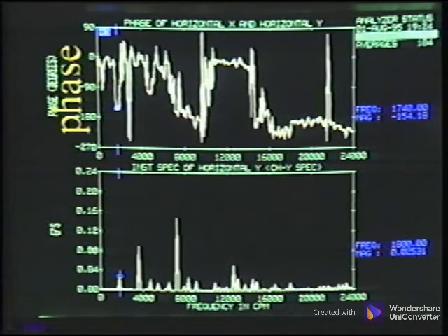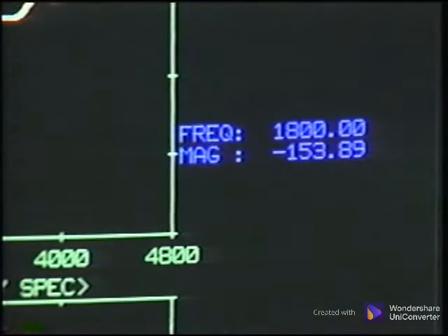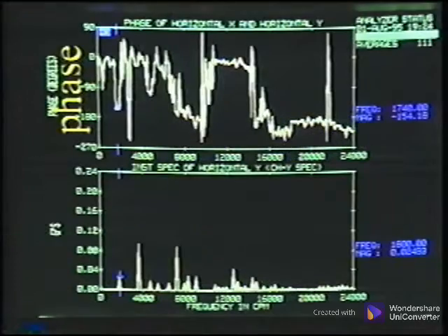Then we can select a particular frequency of interest and have the analyzer display the calculated phase relationship. Notice that we can select any frequency in the spectrum for the phase comparison. Because this capability is here, there is also the ability to display the phase relationship for every frequency in a phase spectrum. This spectrum has frequency as the x-axis, but has phase in degrees as the y-axis.